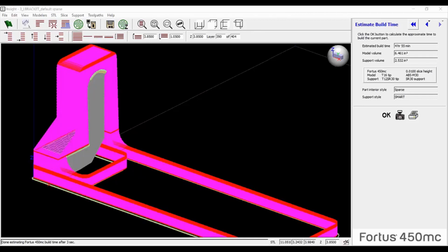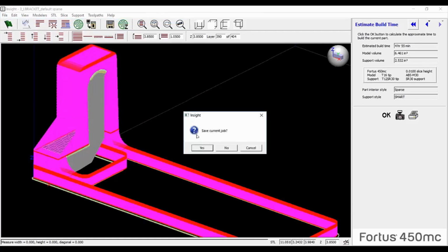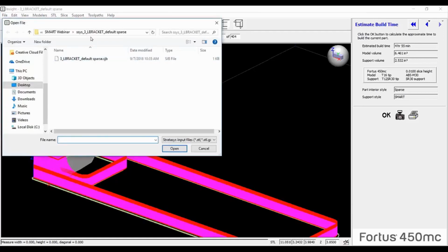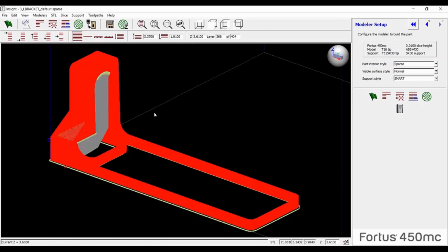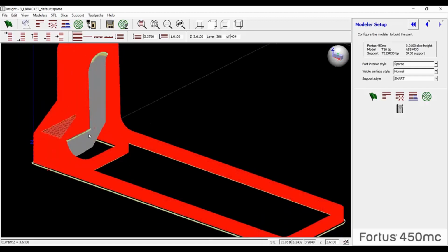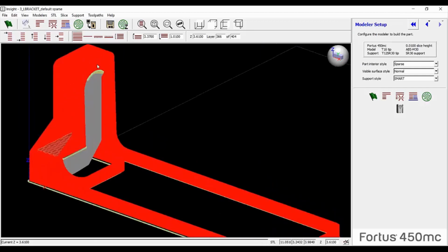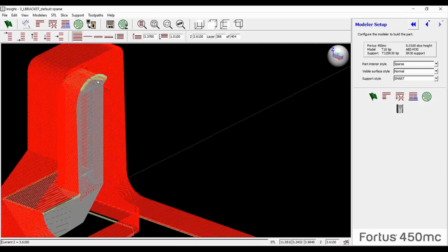So last two, first we're going to do the Z section, and this should have all of the same defaults as the one that we just opened. So I'm going to reopen this guy here. And so we're back to the same default start point as exercise 3. Again, that's a 5 hour, 32 minute runtime. But if we notice here, we're building up this giant support structure, and it goes up and up and up all the way just to support this face in here.